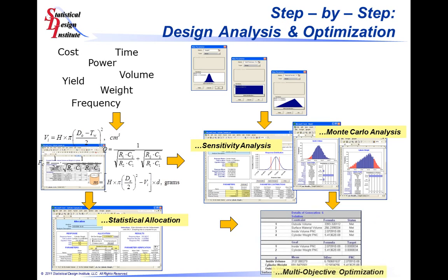And in the Apogee toolset, once you've defined your constraints and goals and the various responses you're analyzing, then we can go perform a multi-objective optimization. You can have a variety of constraints that you may have defined for a particular design. You may have a set of goals that you've identified that you would like to achieve. And the optimization tool will then go through and find what is the preferred value for each of your X parameters. It could be nominals or uncertainties that would be needed to satisfy certain attributes or aspects of your response conditions that go against your specifications.